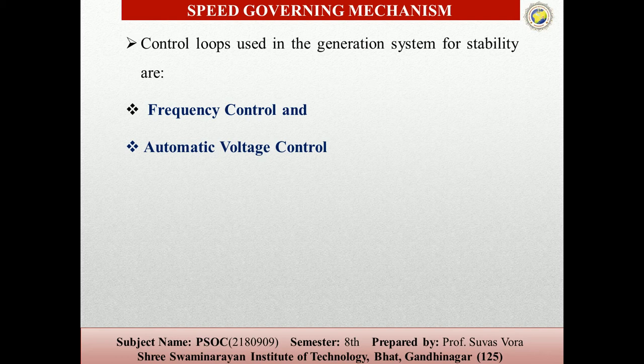But in the case of the hydropower plant, the inertia of the water flowing through the turbine is an additional constraint affecting the performance, which is not present in the thermal power plant. But the basic principle is the same: the speed of the shaft is detected and compared with the reference value, and the feedback signal increases or decreases the power generation. So both systems have the same working phenomena.